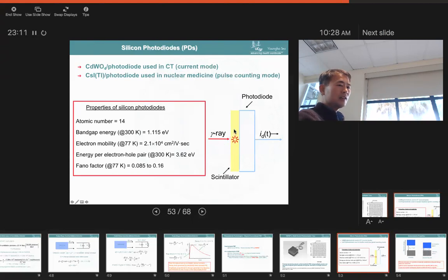So you have scintillation light coming in, and silicon also acts as a photon absorber, and then there could be some charge generated by the voltage applied. You can actually create the electron-hole pairs. They can be drifted and collected to read our signal. This is the simple way of operation. But usual silicon photodiode operation is that we apply a voltage that is not that high, so we are not amplifying any signal within the photodiode. This is the actual conventional operation of a silicon-based photodiode.